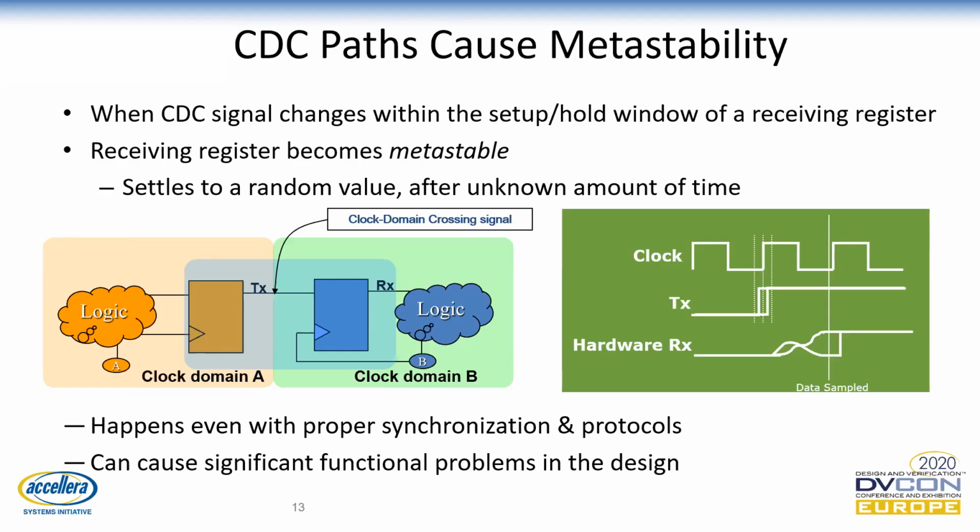Designers must add synchronization logic to prevent metastability from propagating to downstream logic. So in general, we want to prevent the metastability at the blue register from propagating downstream. So by adding a synchronizer, we can do that and protect the design against metastability.